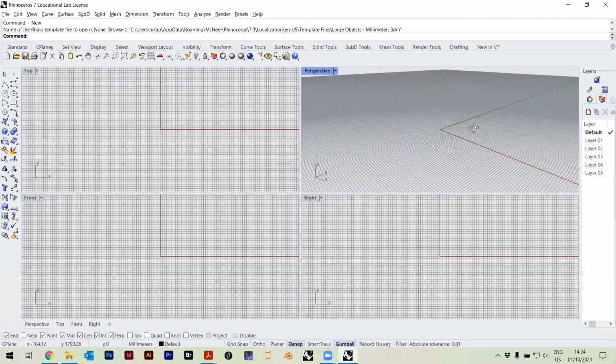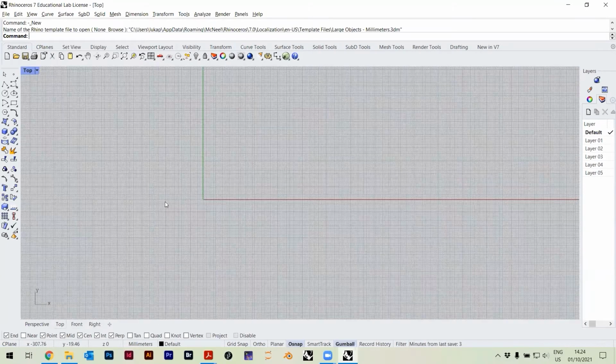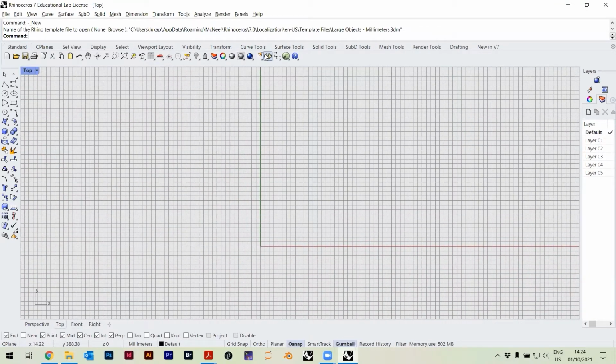With a right click, I can rotate, and these top, front, right, they are basically construction planes. So two-dimensional planes which are glued to these axes. There's the ZX, ZY, and this is XY. In theory, we could choose any of these, but we choose just the top so that all our drawings are drawn in the same plane, let's say.